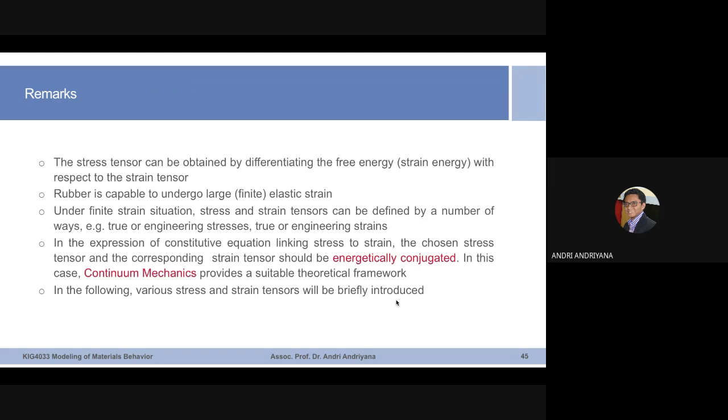For rubber materials, the deformation that we are focusing on remains elastic. But even if the deformation is elastic, we need to choose properly when we talk about stress. If you say that the stress in the material is, for instance, 10 megapascal, then the information is not enough when we deal with rubber. You need to specifically mention whether you are talking about engineering stress or true stress, because the two could be significantly different due to large deformations.